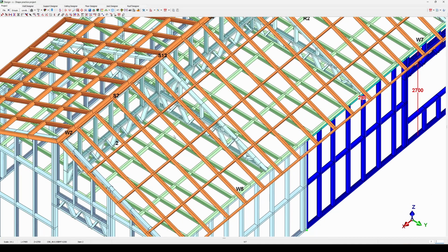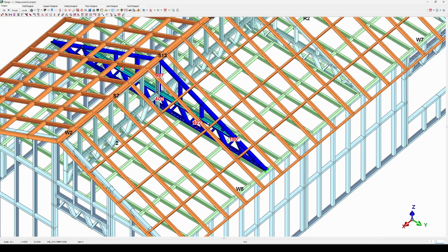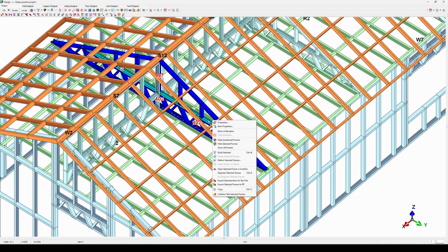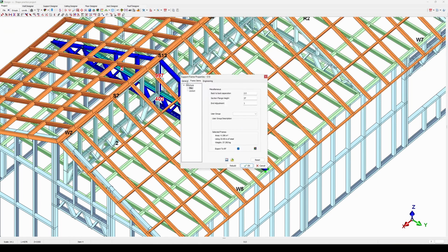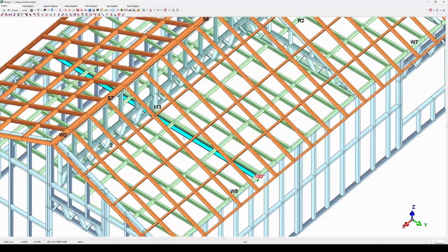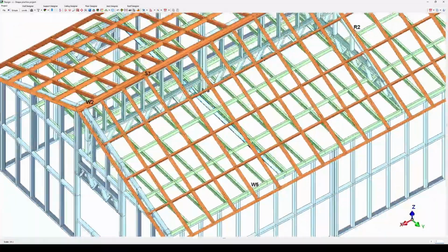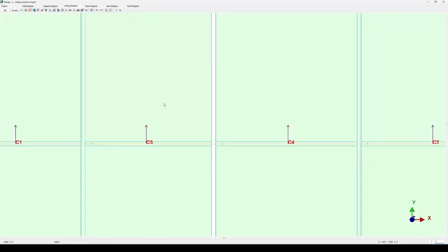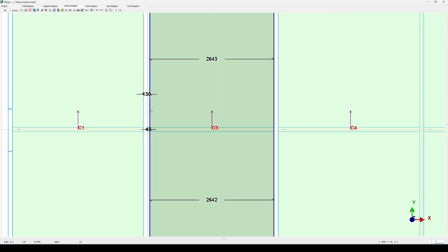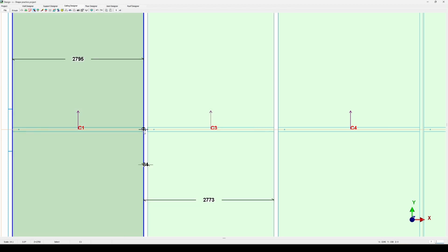If I make that property change on a support panel that has not got that cavity between the ceiling panels right there, by going to the Properties, Generals tab, and changing this to be 2.7 meters, and hit the Rebuild button, it cannot allocate a position to shoot to. So what we need to do is go back to the Ceiling Designer tab and do that same option that we've done on the first one by placing a 1 millimeter gap between the support and the ceiling.